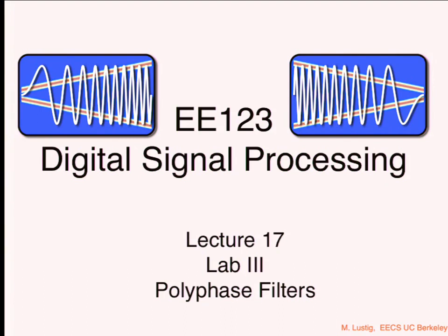Oh, wait. So when I threshold, I get basically noisy coefficients. And so when I reconstruct my signal, it's just a weighted sum of these basis functions weighting the noisy coefficients. And so you just need to calculate what is the standard deviation and mean in the signal domain back. And you'll see that it's much lower. So that's really what the problem is. And good luck with that.